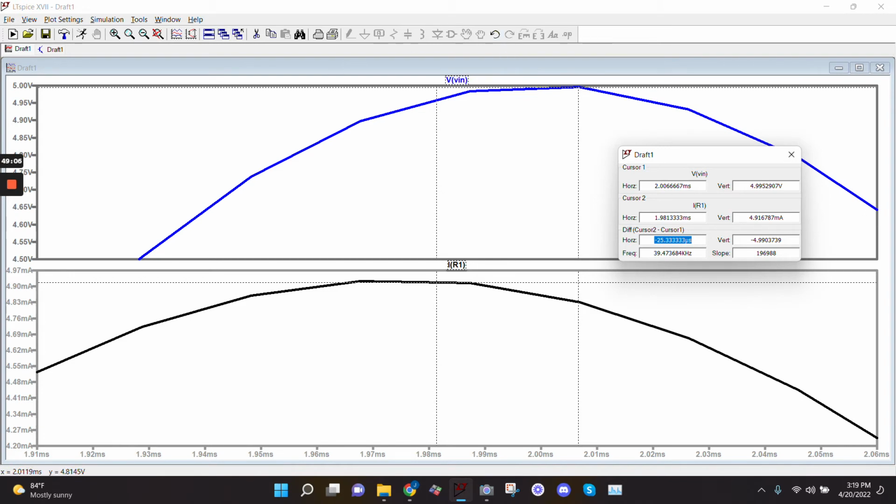Everybody understand why this confirms that my calculation is right? I basically converted the delay in degrees or radians to a delay in time, and then SPICE can measure that delay in time to prove that I got the correct phase. Okay? Do we need to show that from SPICE? I don't know, like a screenshot of that.